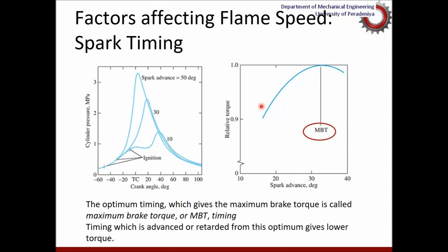So always, when you ignite gases in the engines, it is preferred to ignite at this MBT spark timing, where you get the maximum work produced or the torque out from the engine under that particular condition. But again, there are some other constraints to operate engines at MBT.